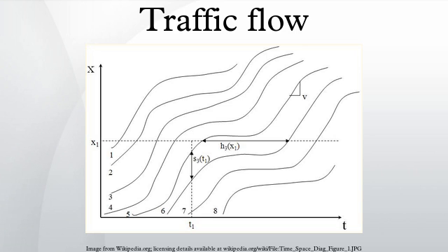For a highway user optimum model considering one alternative route, a typical process of traffic assignment is shown in Figure 15. When the traffic demand stays below the highway capacity, the delay time on the highway stays zero. When the traffic demand exceeds the capacity, a queue of vehicles will appear on the highway and the delay time will increase. Some users will turn to the city streets when the delay time reaches the difference between the free flow travel time on the highway and the free flow travel time on city streets.